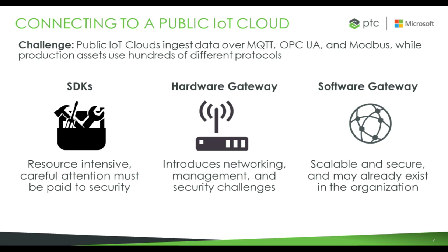Public IoT clouds today natively consume data over MQTT or some flavor of MQTT, and some have developed tools for ingesting data over the OPC UA protocol or Modbus. But in most production environments, there's a gap there. Production environments have all different kinds of controllers that may or may not speak OPC UA or MQTT. Mitsubishi controllers use MELSEC, Siemens controllers use their own proprietary protocol, Allen-Bradley controllers use the Common Industrial Protocol, and sensors and scales may use any number of things, including just a simple ASCII protocol. So the options for connecting all of those disparate devices to the platform are what we show here.